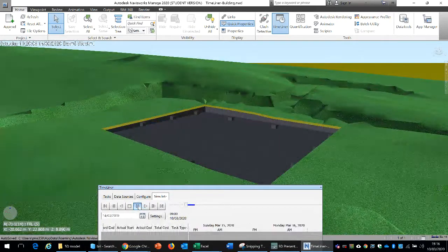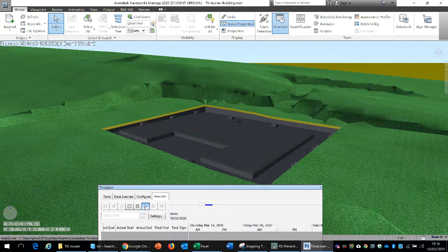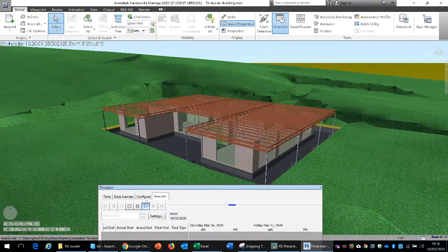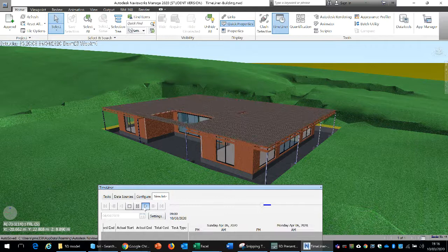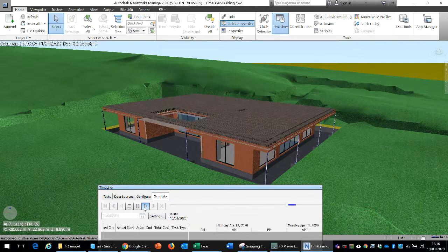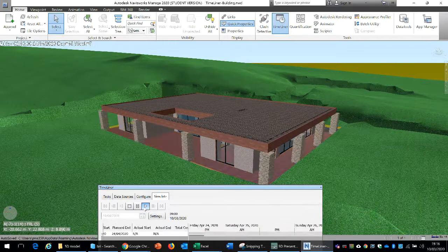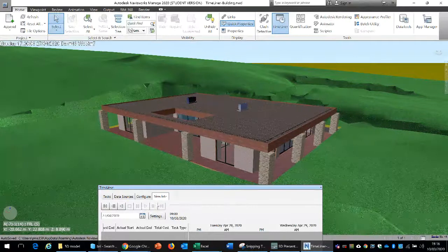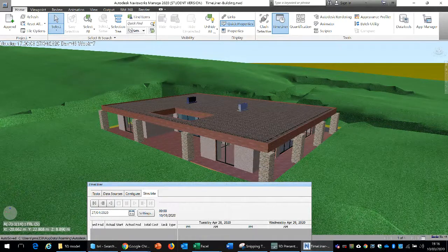So this is now simulation playing. On the top window, you can see the information that we have just selected being overlaid. So we could have maybe cost information or any other tracking information. It will basically go through different phases. So we could break our work into different phases. We could maybe have our site planning and logistics done accordingly. Okay, so this way we learn the Timeliner window.